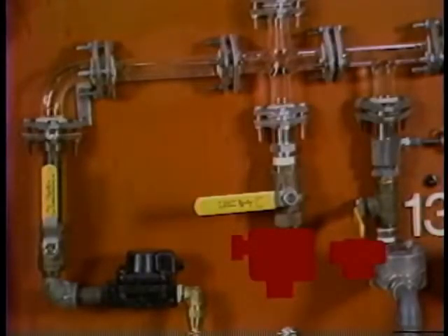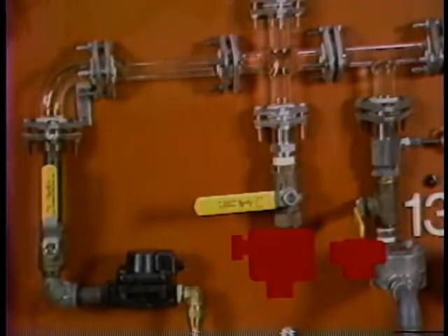Thermostatic and thermodynamic traps react to changes of temperature or changes of state rather than responding directly to the presence of condensate. All traps are required from time to time to handle the heavy air and condensate loads of startup. At startup, the system is cold, devoid of steam, and often has large accumulations of condensate and air in the lines. F&T and bellows traps are most recommended for frequent startup conditions because of their ability to handle large air loads. The F&T and bellows traps are wide open at startup and remain open until the system nears operating temperature.